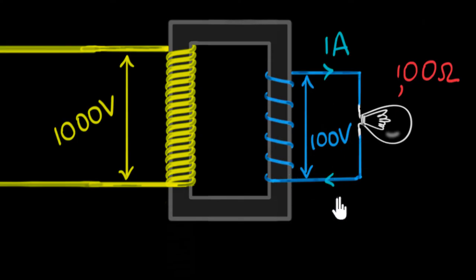It's an alternating current flowing over here. But now the question that I want to ask you is, how much current do you think will flow here? Now that's an interesting question because this is a different circuit altogether. How do we figure that out? Well, we can use one of the basic principles of physics, energy conservation. We can say that, look, in a transformer, there is electrical energy being transferred from here to here. So whatever energy is lost by the charges in this circuit must be exactly gained by the charges in this circuit, if this is an ideal transformer where there is no energy loss.